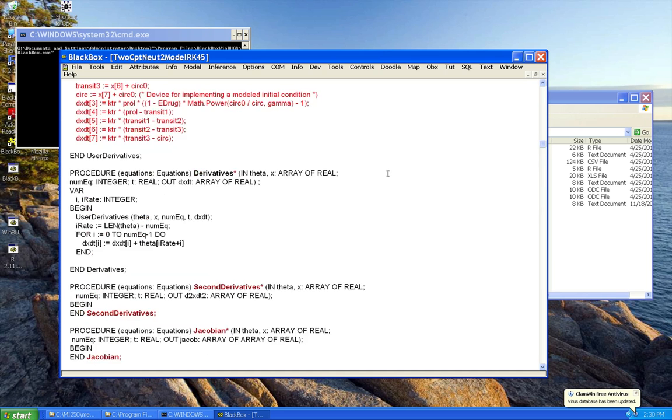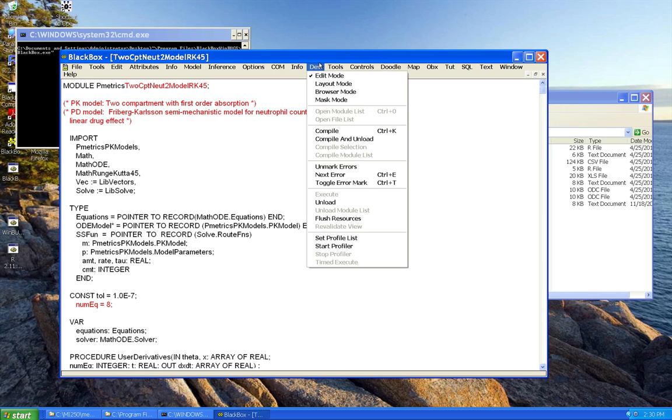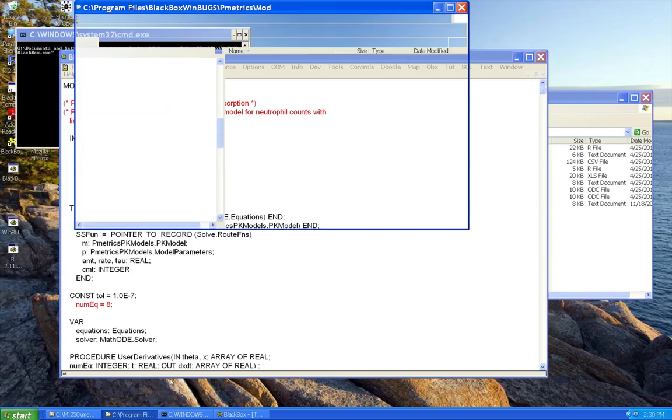So at this point, if you think you got it, then the next step is just to go ahead and compile it. You go to DEV over here, compile and unload. If everything worked out well, you get this little OK on the bottom. So we're all set there. And then, as before, we also have to create our WBDev component here of the same name.